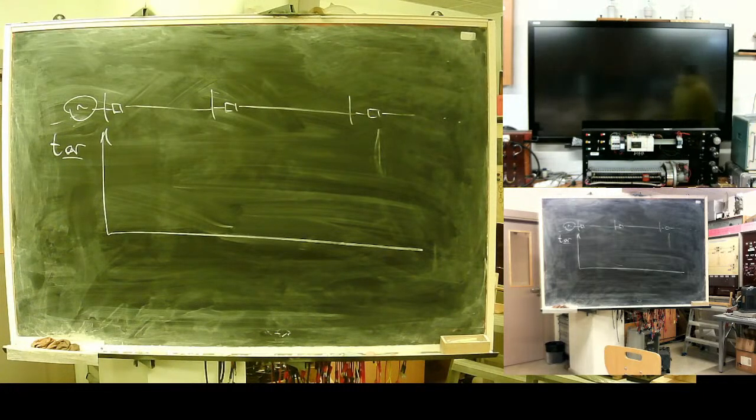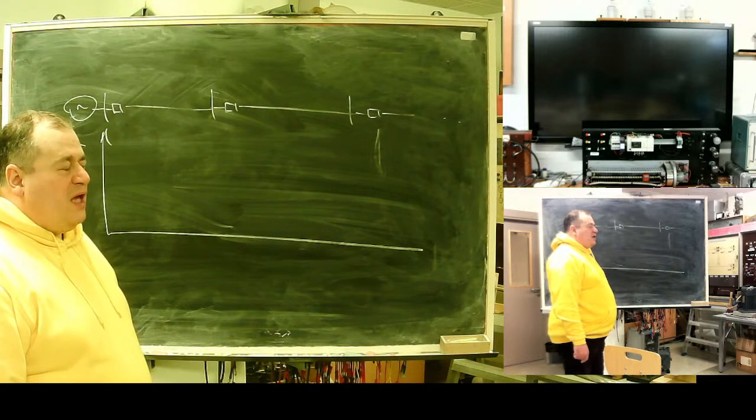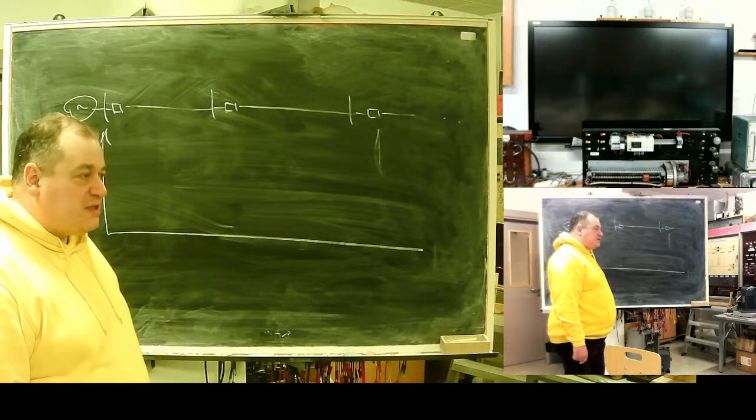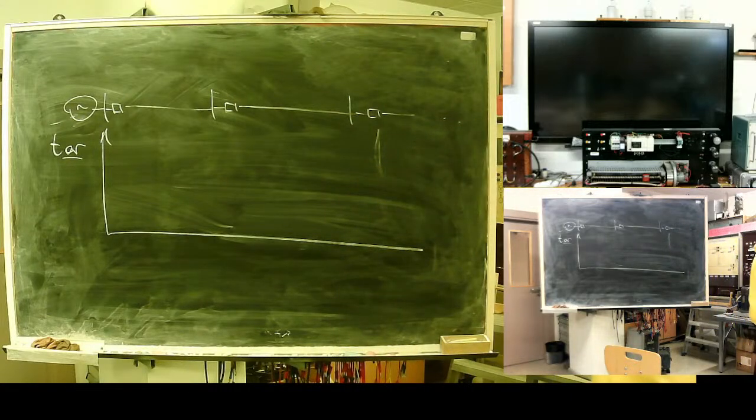see, we are very conservative in our design approach. So reclosers may fail. One of the things that may happen: old types of reclosers are prone to freeze. During a very cold winter, they freeze and can misoperate. So as a backup, one thing can be done: minimum voltage protection. In case of a fault, voltage drops seriously, and this acts as one more backup stage.